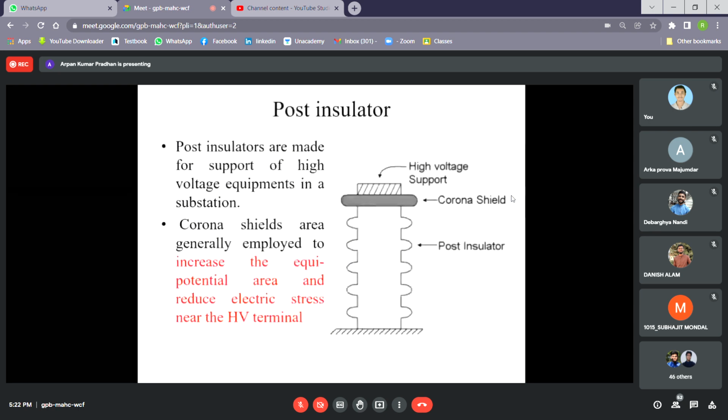When there is a transmission line voltage, the atmosphere surrounding the transmission line gets ionized. Definitely there will be a hissing sound, violet color, etc. But do you know why this corona actually occurs? This is due to the high electric field intensity adjacent to the rough surface of the transmission line. So, high electric field intensity.